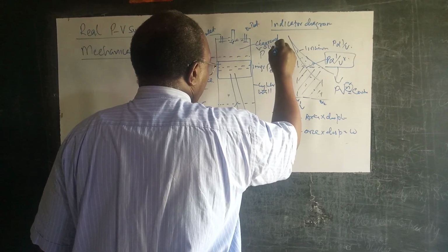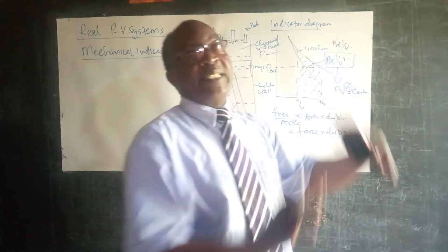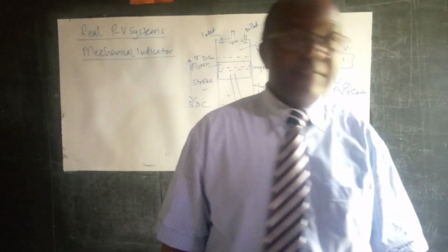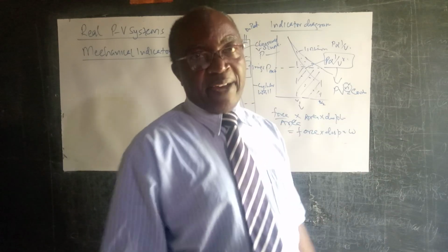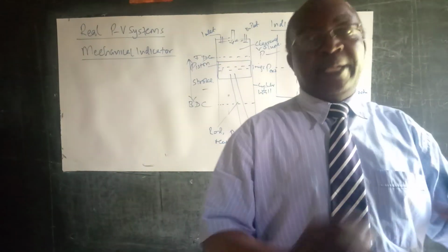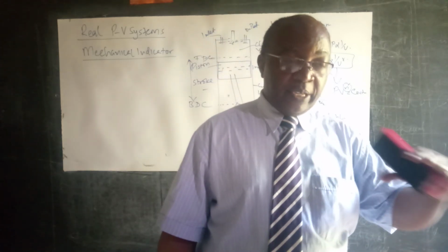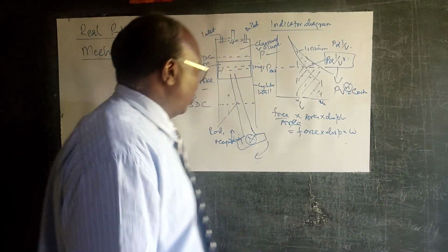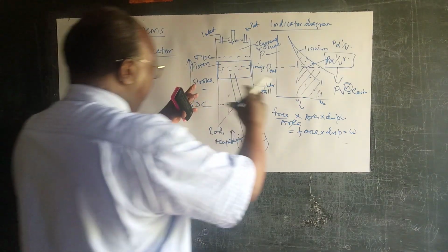This clearance volume is very important. If the piston is not to collide with the cylinder head, then that clearance volume is necessary. And of course, the operation of the valves also has to be cleared. The valve clearance must be as per specifications for that particular engine. So it is very important for us to remember.